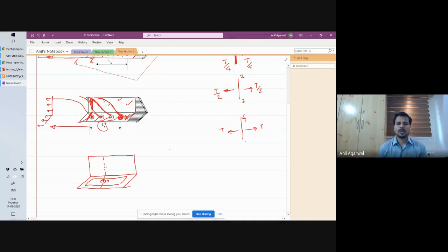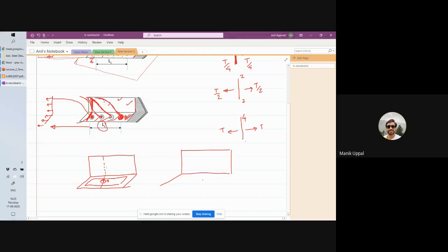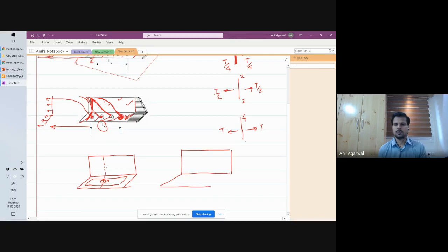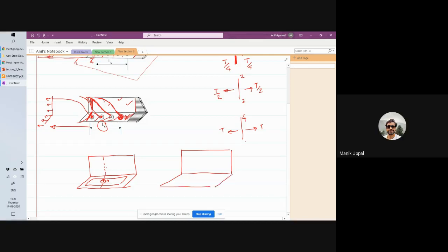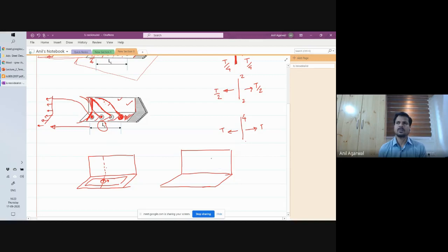Fine. What else may play a role in controlling shear lag effect? Bolting the outstanding leg with that plate. If you're bolting the outstanding leg, then there is no issue at all. There is no shear lag. So if your gusset plate is connected only to, this is the outstanding leg.